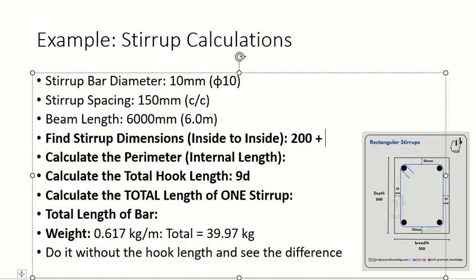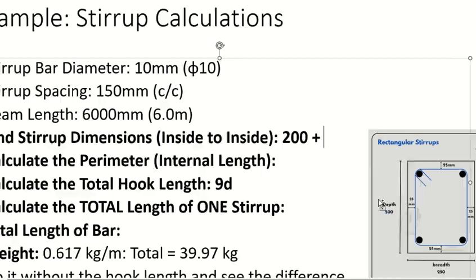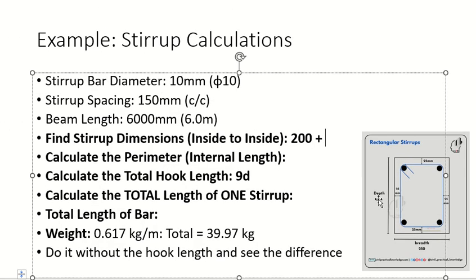This is the horizontal length, and then we have the vertical as well, right? So again we will do the same thing. What is it? 500. So doing the same thing, 500, 25 on the top, 25 at the bottom. You subtract it, you get how much? 450. So this is the inside length which we have available.